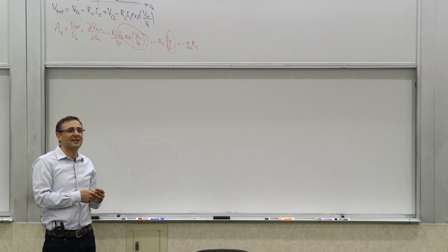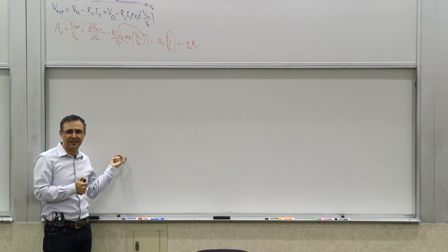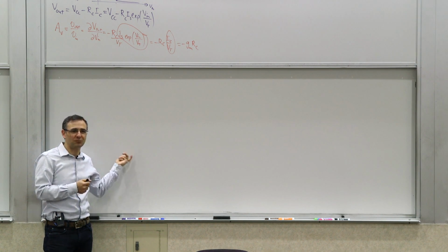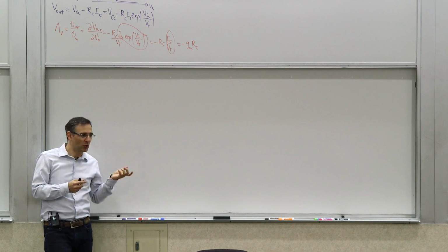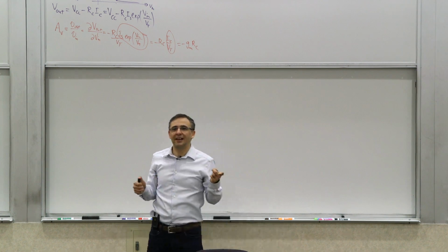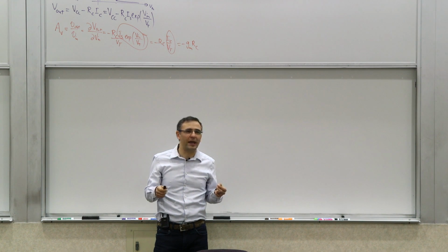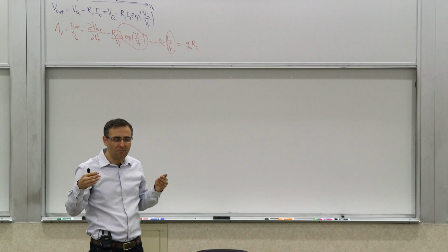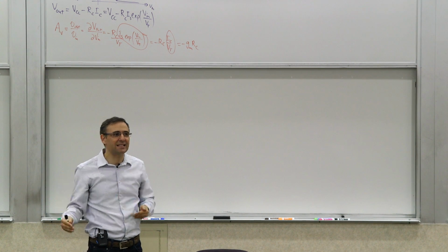If your source or your emitter is connected to a fixed potential, the pi model usually is more helpful. If your source or your emitter, or terminal 1 in the arbitrary device, is not connected to a fixed potential, is connected to a resistor or something like that, where that terminal can move, almost 99% of the time it's easier to use the T model.